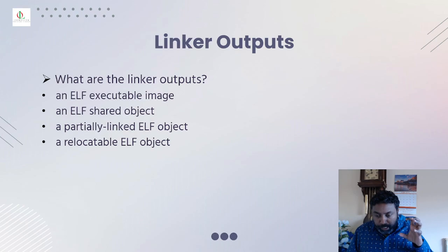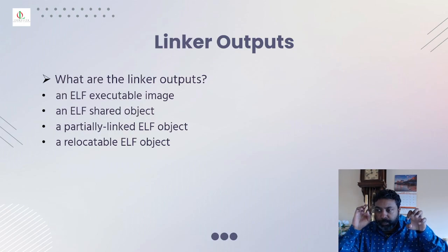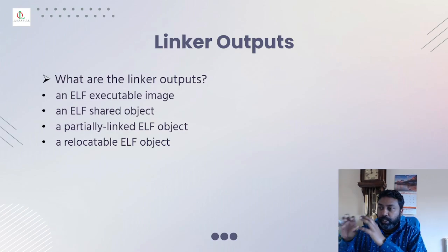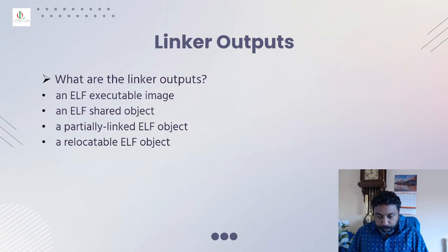The linker file customizes the sections to a particular memory, and it links by mapping those to the object files and assigning addresses to those object files. It groups them together and links them to be used as an executable format. As you already know, the linker script is a text file, which is why you downloaded the GNU toolchain in the previous session. It will give you all the necessary files, and if you want to use the command prompt, you can use